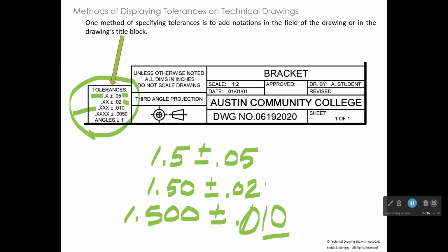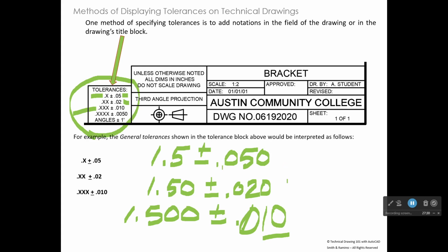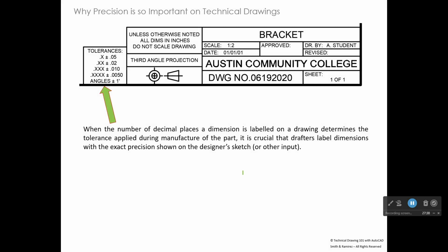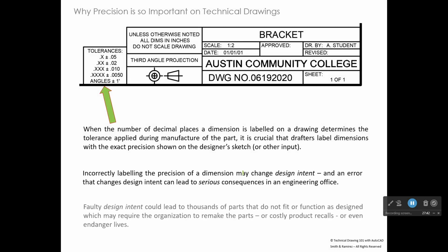And if they look at this tolerance, they're going to put another 0 and they're going to call that 20 thou. And they're going to add another 0 to this, and instead of calling that 5/100ths, they're going to call it 50 thou. And they mean the same thing. And so I always point that out to students because, when you get into a machine shop and all of a sudden the machinist is using a different language than you have, it's a little confusing sometimes.